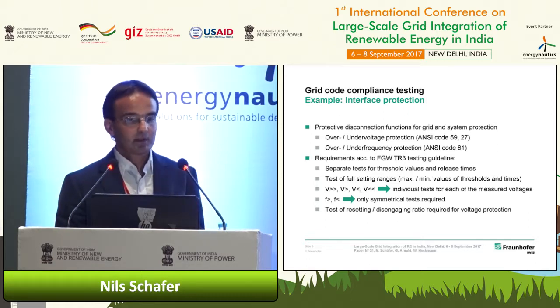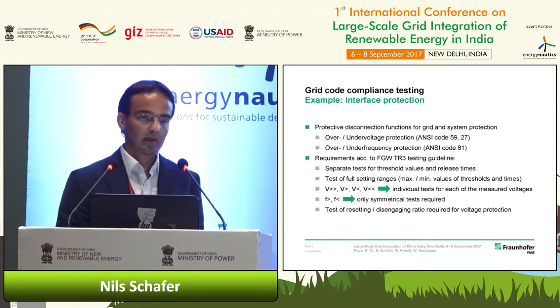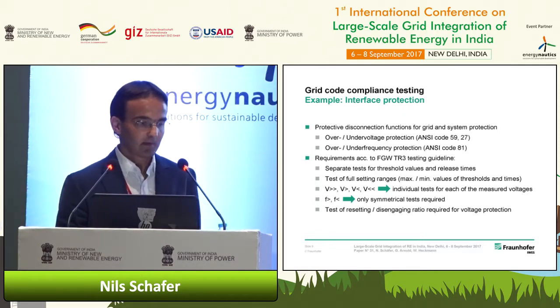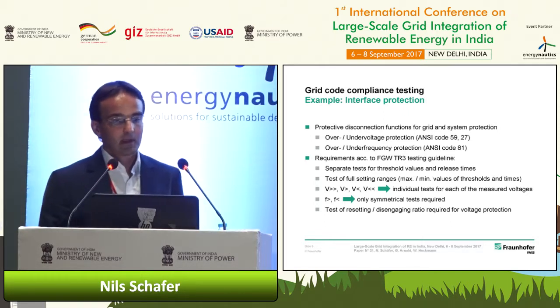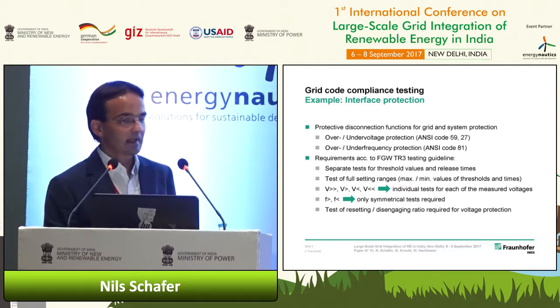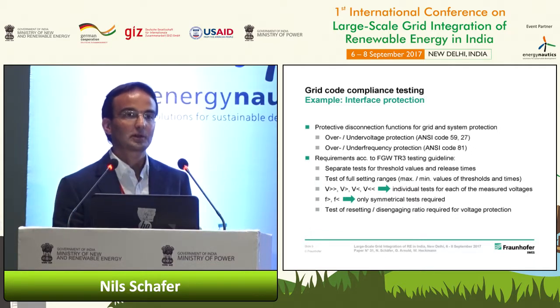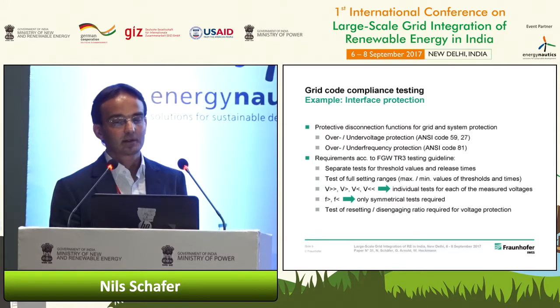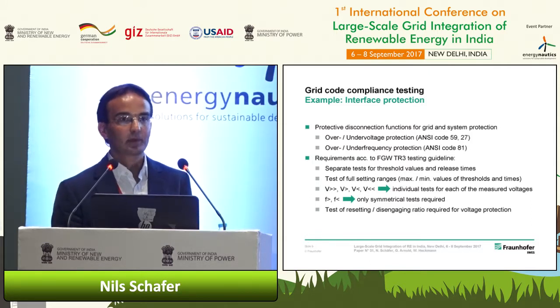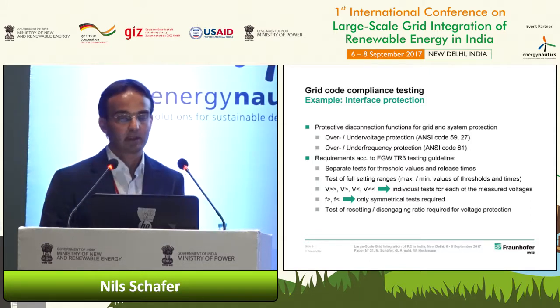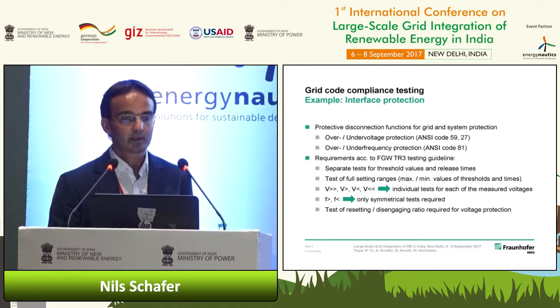For this protection, it considers the disconnection function of the inverter or the wind turbine. So here, the tests have to be performed for the threshold value and also for the release time. So separate tests have to be done, always for the full setting range.